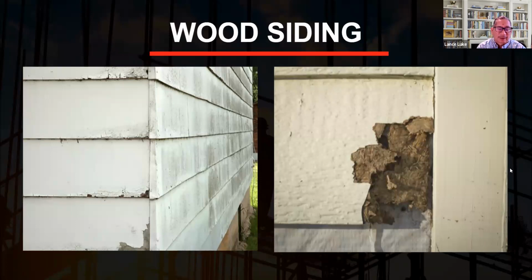And I like to call it cardboard siding because it acts like cardboard. It doesn't withstand, it never lasted. And the brand names could be LP, Louisiana Pacific, Masonite. Masonite siding was a well-known brand that was extensively used in the 70s on single-family houses and townhouses. Now in Hawaii, Kailua, Mililani, single-family houses and townhouses use this type of siding, and it's all subject to failure. You've got to keep it painted, and even when you keep it painted, it still rots, so you have to replace it.